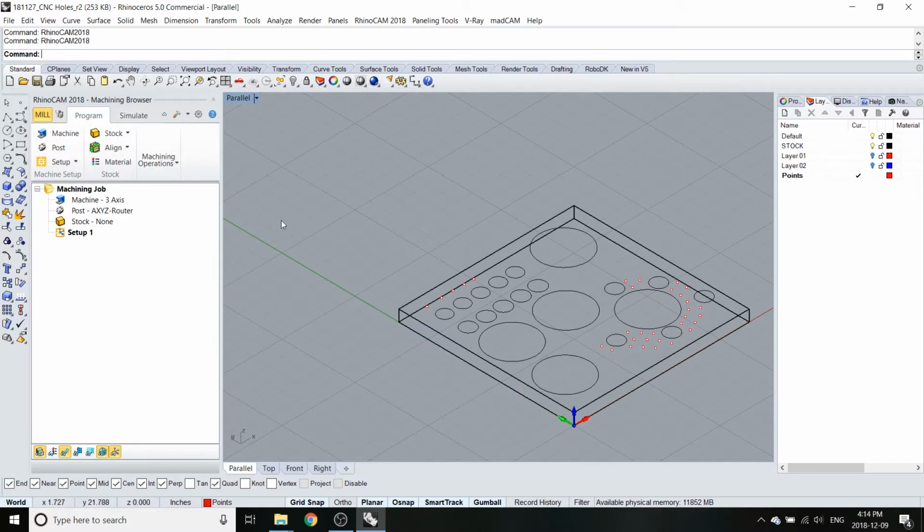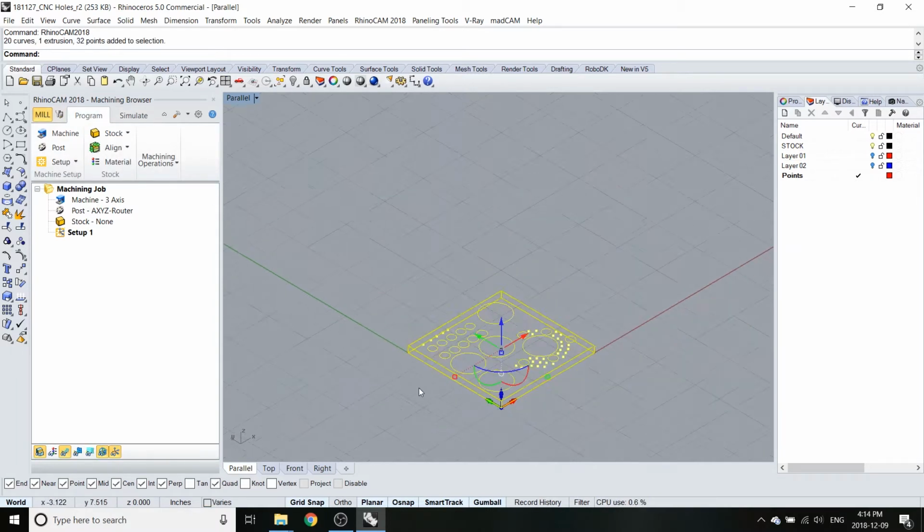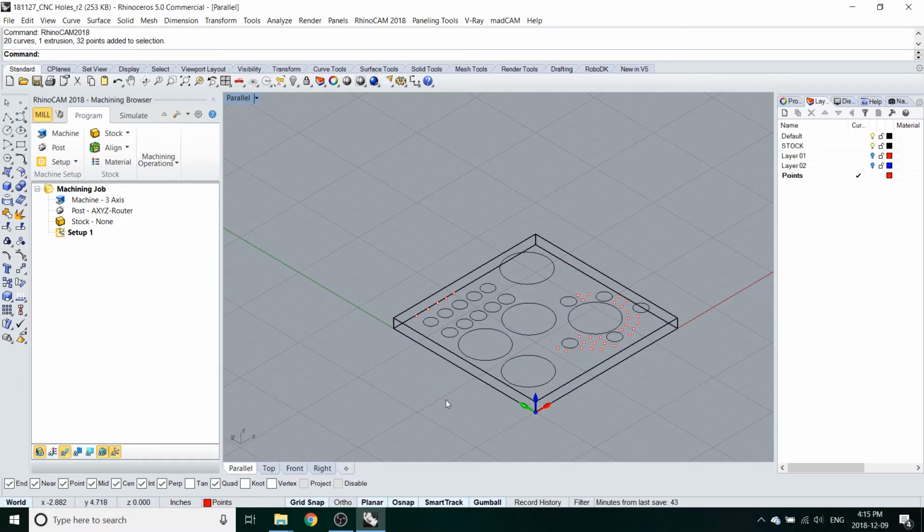It is important to have only the relevant material in the CNC file. Make sure that the CNC file contains the stock material and geometry for the toolpaths to pick up. This will ensure that any automatic setups won't link to irrelevant geometry that is within the file.